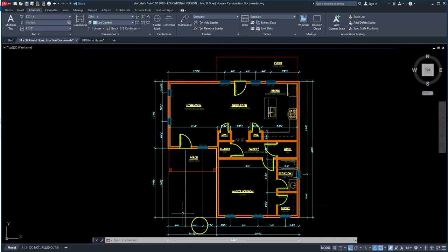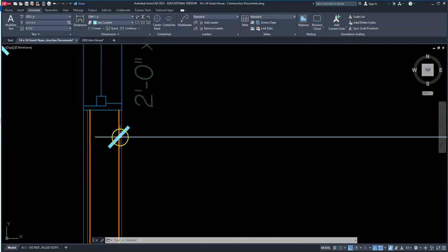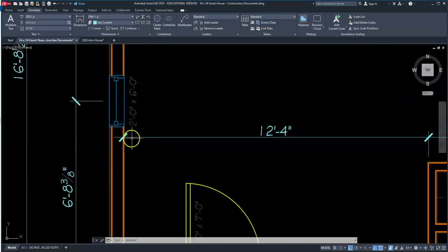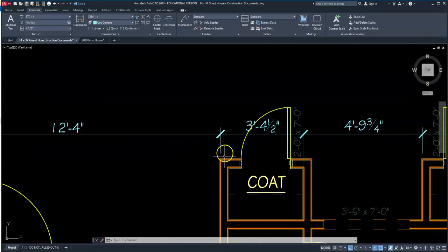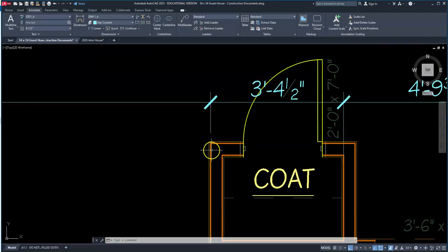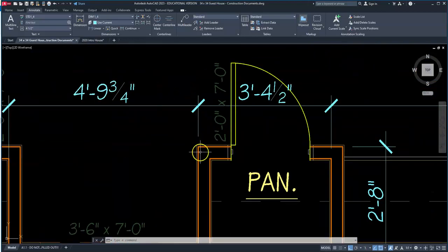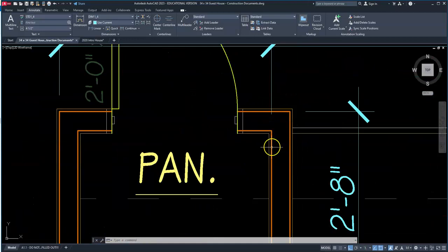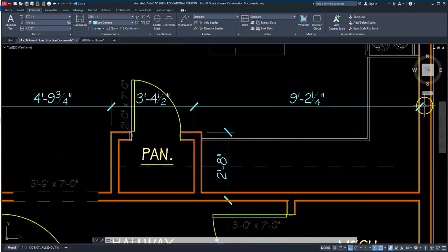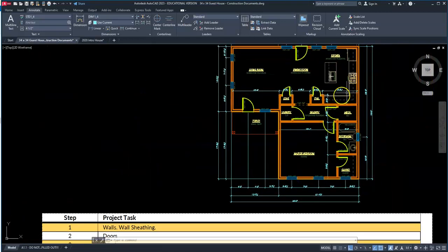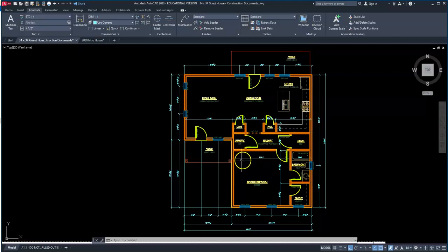Okay, so once you've done all of the dimensions on the outside, you'll do the same for the inside. You'll select the stud wall again on the inside, and then you'll take the line across and you'll grab these inside corners. We're going to go on the left-hand side, here and here, across to the left-hand side here, left-hand side of the wall here, and then across to the middle, or to the inside of this stud. So you'll do that across here, across this section here, and then a vertical section here.